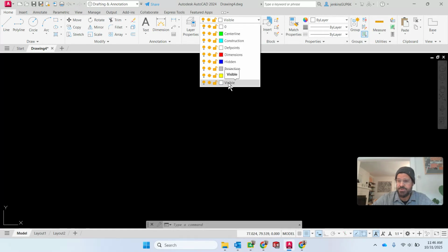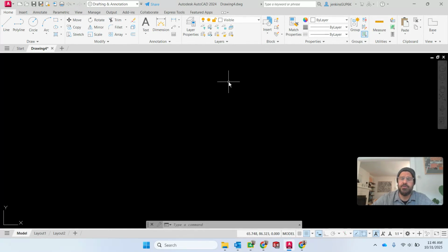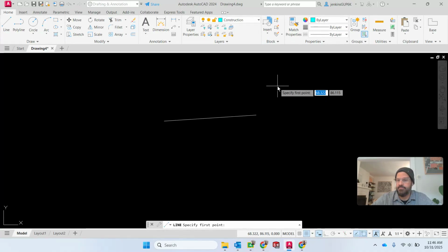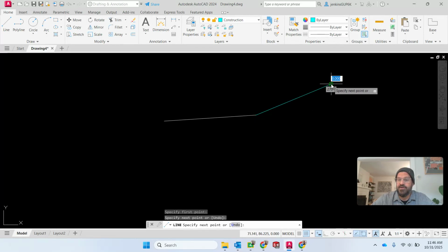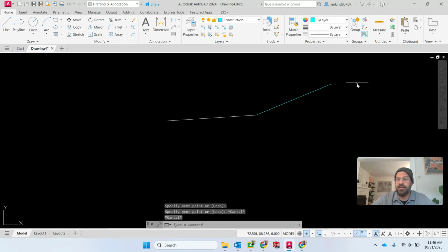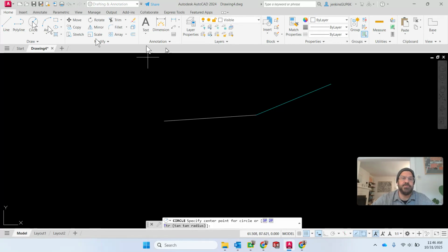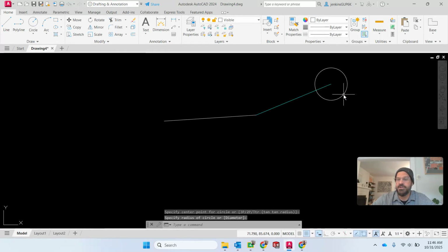So as you start your drawings, one of the first things you would probably want to check is that you click visible. That means that when you make a line, it's going to show up as a white straight line. There are other types of lines. Construction lines allow you to just draw lines that you can turn on and off that help you locate different things. Say I wanted a circle to start right here. If I drew a line from there to there on the construction layer, I can define where that circle is going to be.